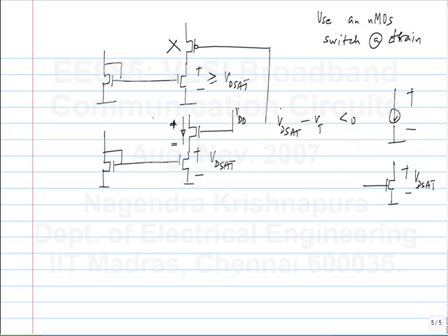So the total voltage is going to be more than VDSAT plus some V switch. So the compliance will be reduced. That means that some of the other signal ranges or common mode ranges will be reduced. That's what happens when you increase VDSAT, right? So for a smaller range of voltages, it will go into triode region.